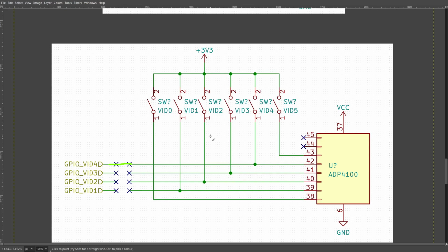You can try to overpower it with switches. So for instance, instead of just single pole, single throw switches, you'd use a dual pole switch that would alternatively connect to ground. And that way you try to overpower it by connecting it either directly to 3.3 volts or directly to ground and try to overpower this GPIO. That has all sorts of issues with it. I would avoid that if at all possible.